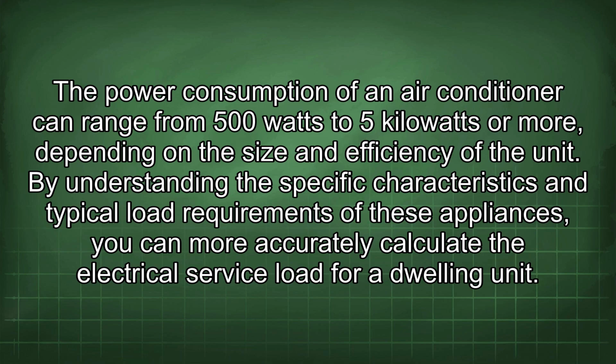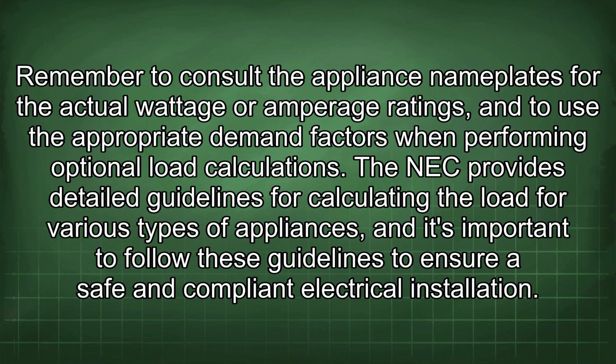By understanding the specific characteristics and typical load requirements of these appliances, you can more accurately calculate the electrical service load for a dwelling unit. Remember to consult the appliance nameplates for the actual wattage or amperage ratings, and to use the appropriate demand factors when performing optional load calculations. The NEC provides detailed guidelines for calculating the load for various types of appliances, and it's important to follow these guidelines to ensure a safe and compliant electrical installation.